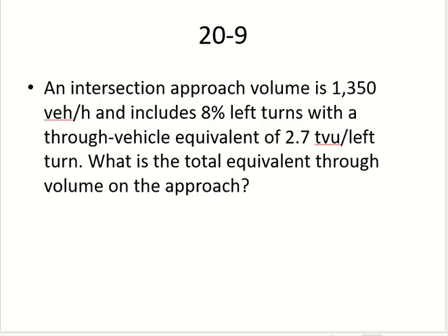So what should I do? First of all, I will find out what my left turning volume is. My left turning volume is 8% of 1,350, which is how much? 100. These must be multiplied by the equivalency factor, so they will become equal to through. Which is how much? 2.